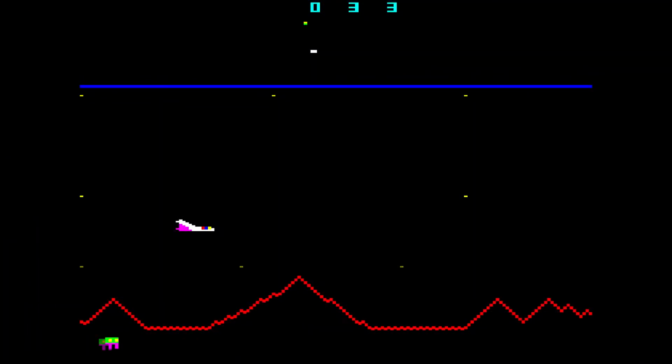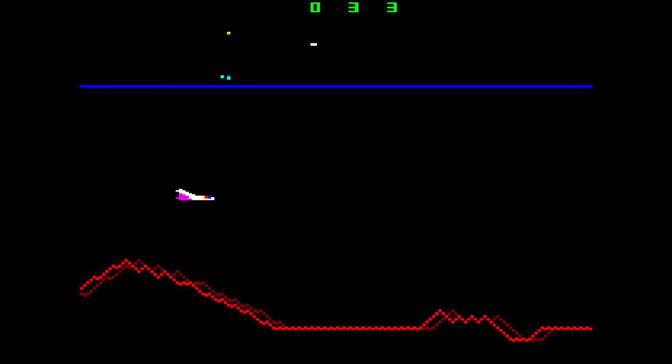I haven't really been through all of the CRTC registers and the sorts of things you can do with them, but two of the registers in particular, registers 12 and 13, deal with the start address in the video memory that the CRTC will start generating the image from. And systems like the BBC Micro, and I don't know about other systems that use this 6845, but certainly the BBC Micro, use this to do hardware scrolling in a lot of games.